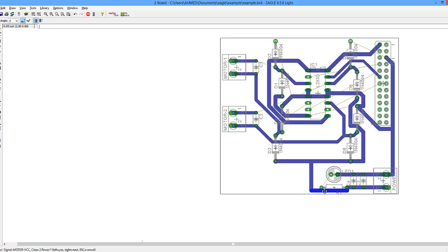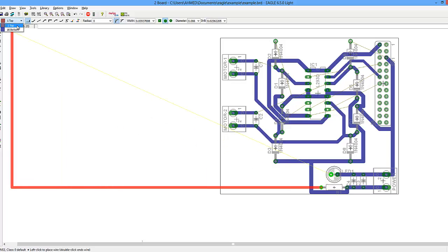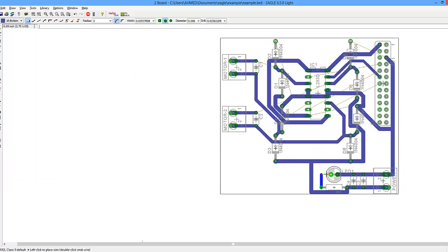Okay. Let's move it a little bit down so it doesn't touch the resistor leads. Yeah, good. See, problem solved. Could have done this easily, but it chose to make it more troublesome for us. Not top layer, bottom layer. So this connection, I will do it myself. Done. This problem solved. You should try to make your PCB all top layer at the beginning. If you can make a bottom layer, if that works, it's awesome. You're halfway done already.